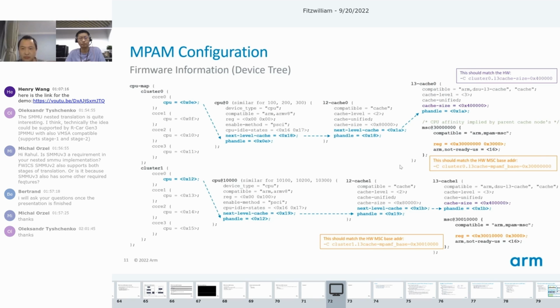I think here the thing is, in theory, you could have several guests using the same partition ID. You could create a group of guests that would share an amount of resources. Because if you are on a safety example, what you want is to isolate some resources for one or several safety domains and let the rest of your system use what is remaining.